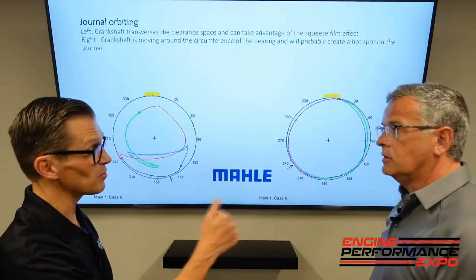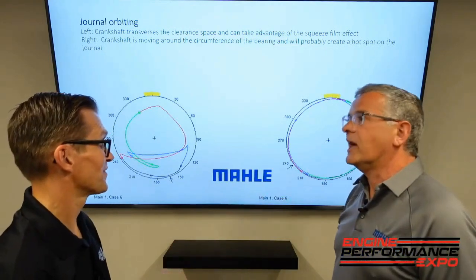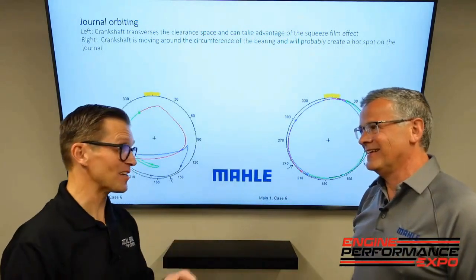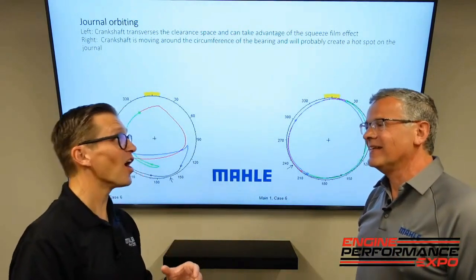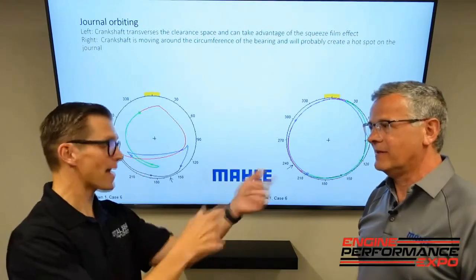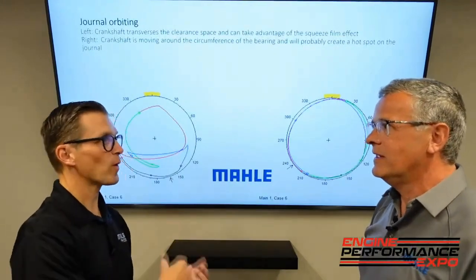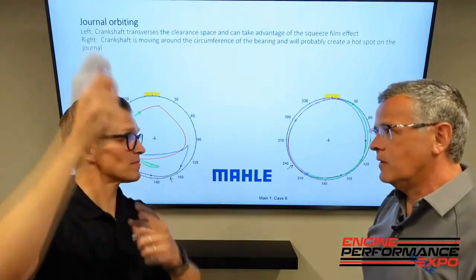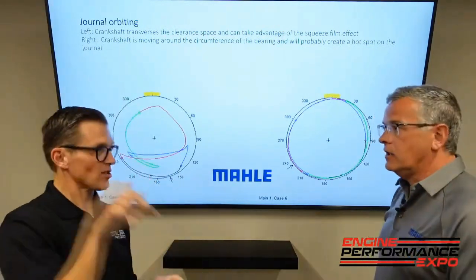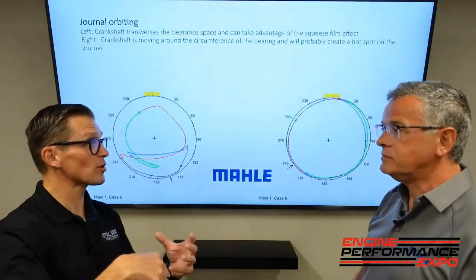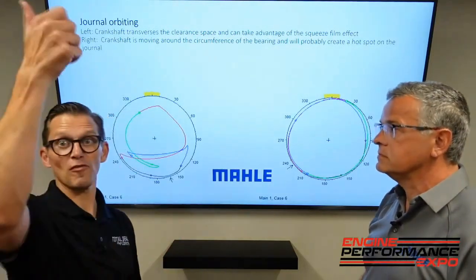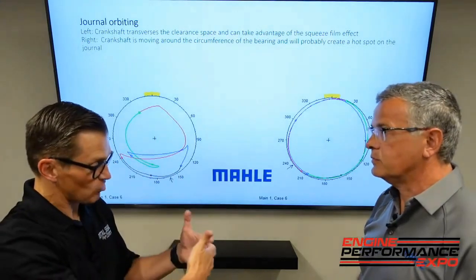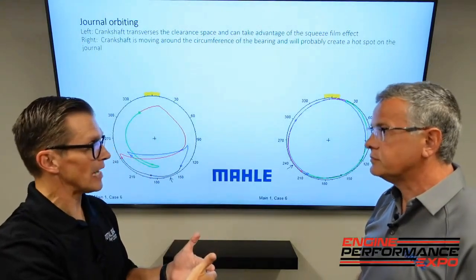Well, that was the big deal in the restrictor plate motors. Yes. That where the main bearing wear wasn't on the lowers, it was on the uppers. Actually, my bad. It was on the lowers where it was the piston rod is trying to go out the cylinder head. Absolutely. The exhaust valve opens, and there's so little cylinder pressure that piston's going up so fast, it's trying to just yank it out, and then it was actually just killing that lower.